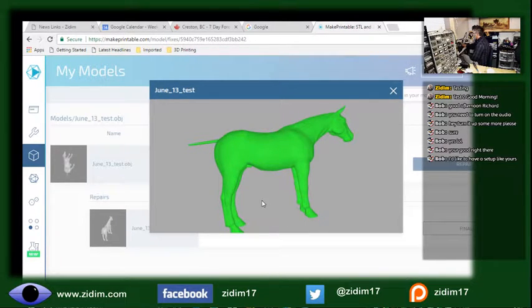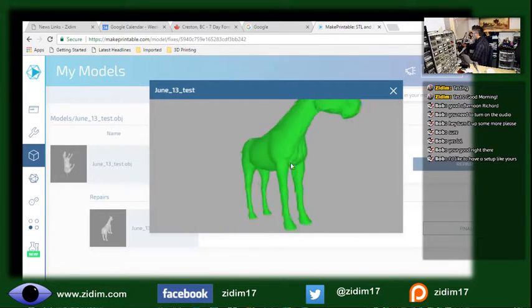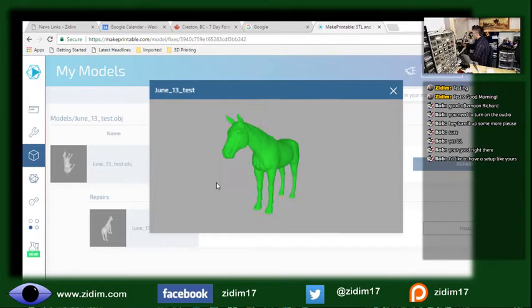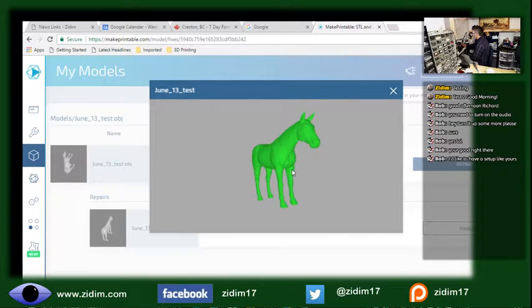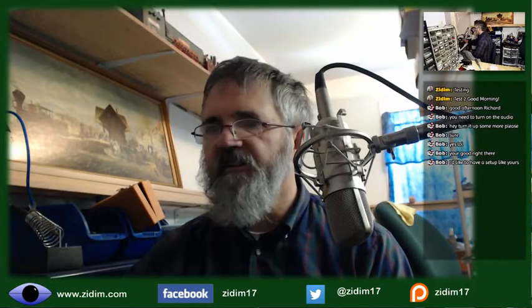And one of the problems that I was finding was within DAZ, the default settings, when you go to export an STL or an OBJ, it takes your camera angle and just sends out what is visible in that angle. So for a shot like this, all this was missing. It was hollow. As I said, I think I got that working, and we're happy with the results from there.